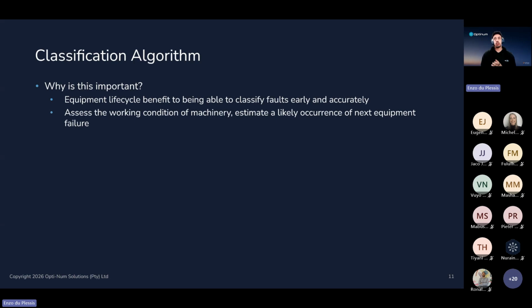So in predictive maintenance, what we do is we place sensors on the specific machine and record lots of data on it. And this can be massive data sets. And then we build predictive maintenance models that will be able to, to a certain level of accuracy, predict what's called the remaining useful life of that specific machine.